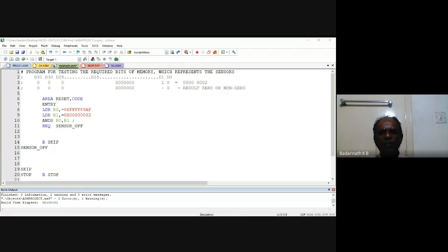To avoid this, like a comparison operation, whenever you do a comparison operation instead of subtraction, it is similar to subtraction, but your destination operand will not be modified, while the flags are still affected. The same thing is given here, what is called the test instruction, TST. What will the test instruction do? The test instruction basically performs an AND operation, but does not affect the destination register. That is why it is called a pseudo AND operation.